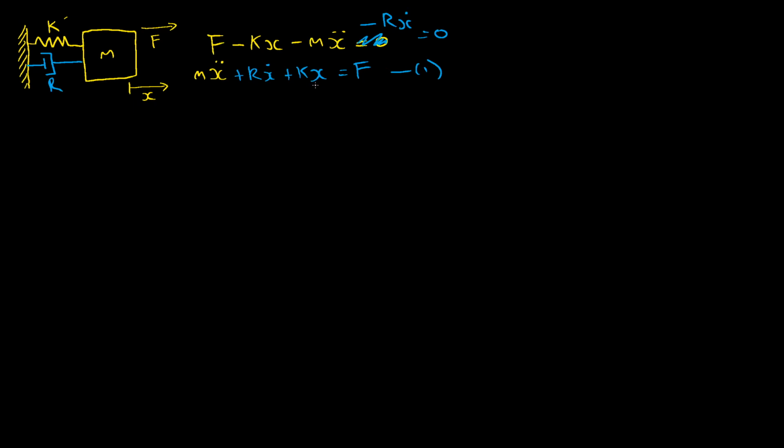And we can once again swap it across to the frequency domain. So we'll take our Laplace approach that we did before. So we have m second derivative, so s squared X(s) in the Laplace domain, plus r s, first derivative of X, plus k, no derivative of X, is equal to F(s). And we'll gather up terms again.